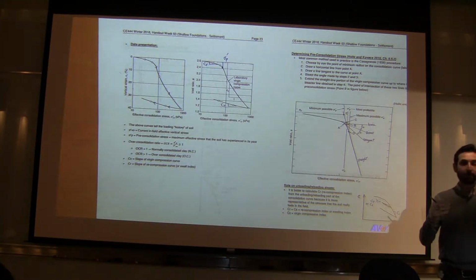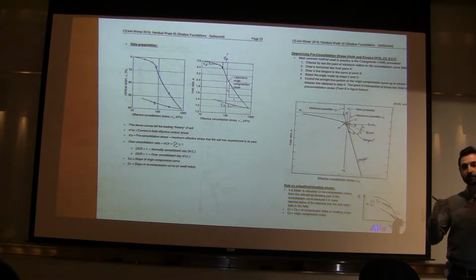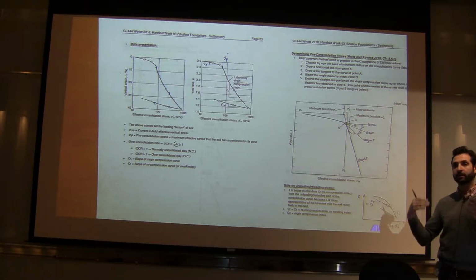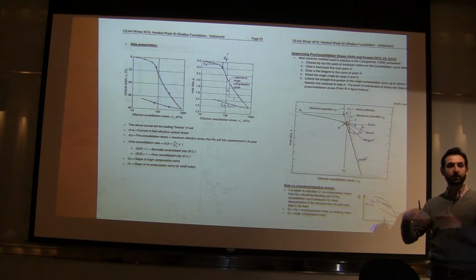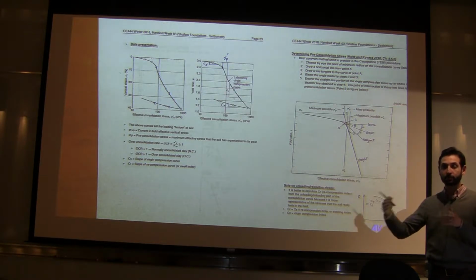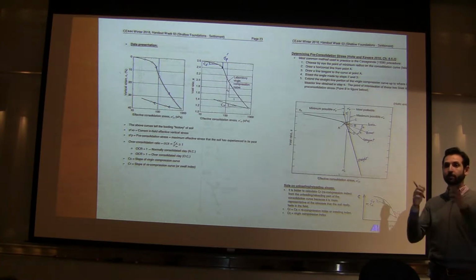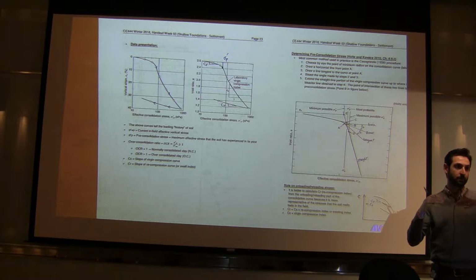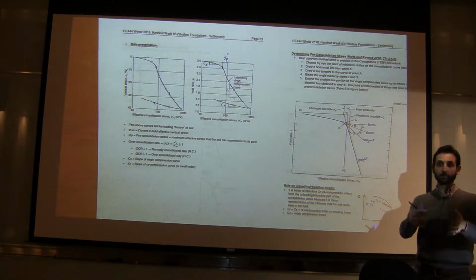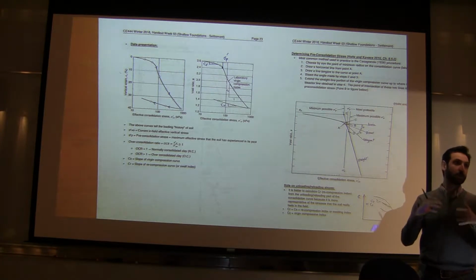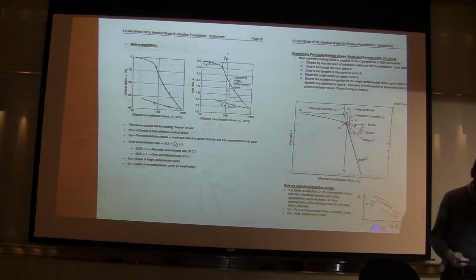You keep applying the load, wait enough until it's done, and then the next load, wait enough until it's done, and then the next load, wait enough until it's done. So you do the consolidation settlement in increments, load increments. And then you unload it. You pick up the load, you wait until the opposite of consolidation, so it starts to heave. It's done, and then you pick another load, wait long enough, and you pick another load, wait enough.